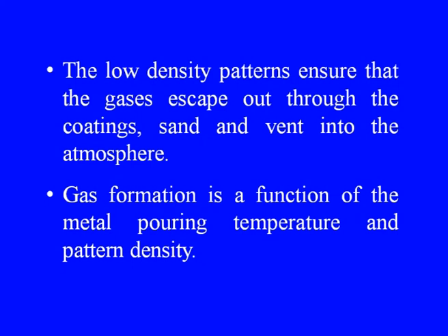Gas formation is a function of the metal pouring temperature and pattern density. If the gas forms faster than it can vent, a defective casting will be formed.